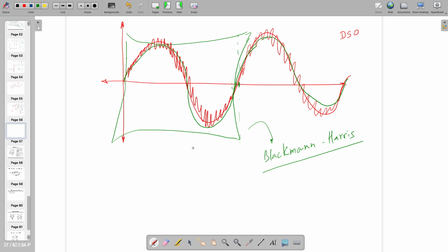Similarly, if you are in sigma delta where you are dumping all the noise to the output side, which kind of window do I need to use? What do you think? This question is for Himanshu because he is designing sigma delta. So rectangular will not work.